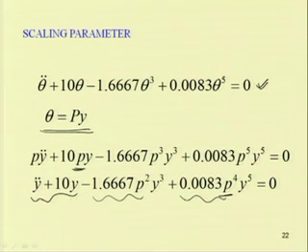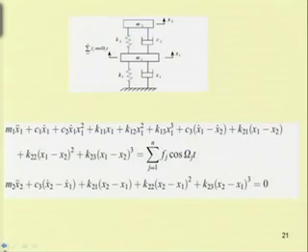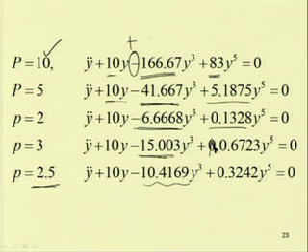In this particular example, as we have p square and p fourth, by taking different values of p, whether positive or negative, we get only negative coefficients. That is why we will not get a positive term or positive coefficient, and so the spring type, if we compare this with a Duffing equation, will show the response of a softening type of spring.